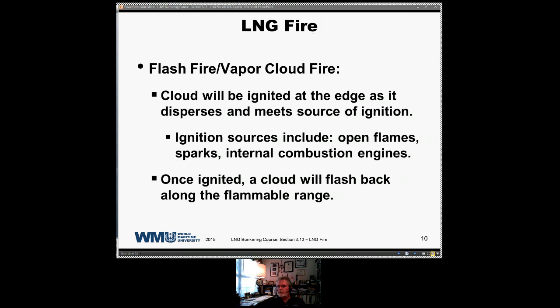We have all sorts of vehicles transiting and riding around. Very much aware of this issue within a refinery, for instance. And even in refineries, unfortunately, over the years, there have been instances where personnel have gone into an area where they had a vapor cloud of some type, have failed to turn off the engine of their vehicle when they've approached it, and it's resulted in fires which have resulted in loss of life and serious injuries.